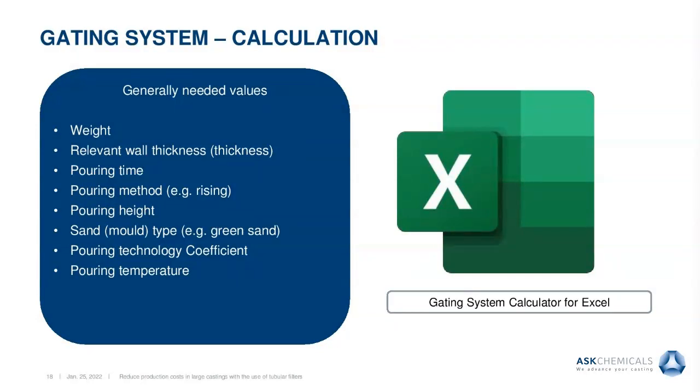You have to keep in mind that the cooling temperature for this type of steel is lower than, let me say, low or high alloyed steel. So it's no problem to use the filters for that. Maybe what you also have to mention is that, as far as I remember, this steel is very liquid when casting, and you also have to consider that when choosing the right porosities.